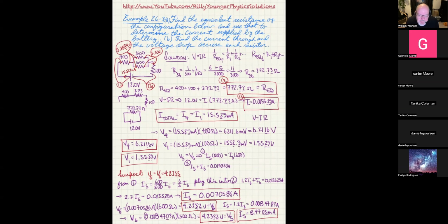So this is sort of a higgledy-piggledy way of solving a circuit. It's sort of convoluted, but it's fun. I mean, I consider it a nice problem-solving skill. And the fact that it leaves you a back door to check things, like, does the voltage in any one complete circle add up to zero when you put negatives as drops and positives for increases in voltage, and use conservation of charge, of course, for the junctions so that the currents add up properly.